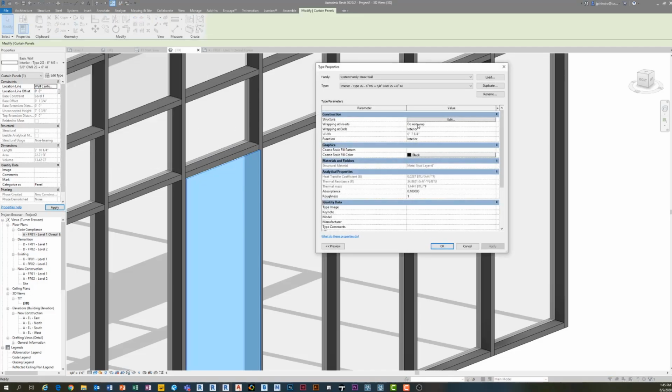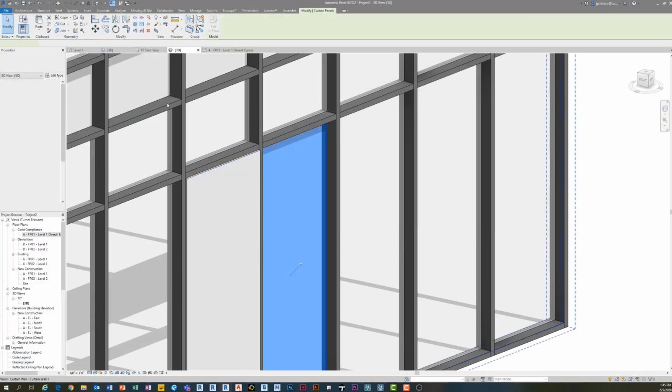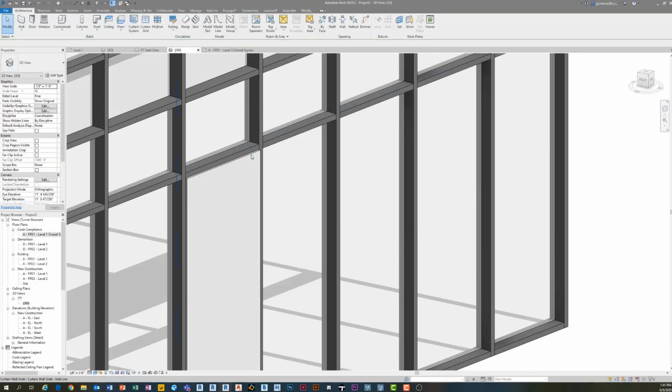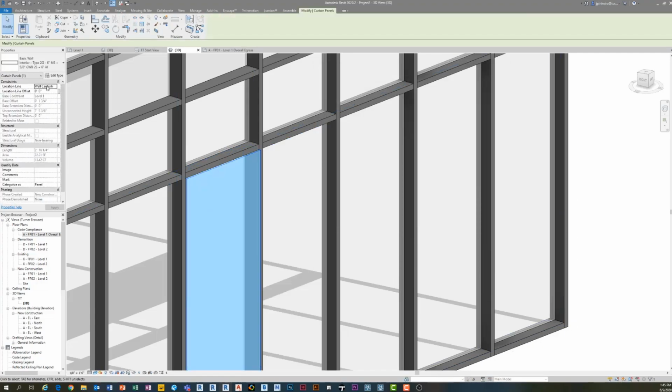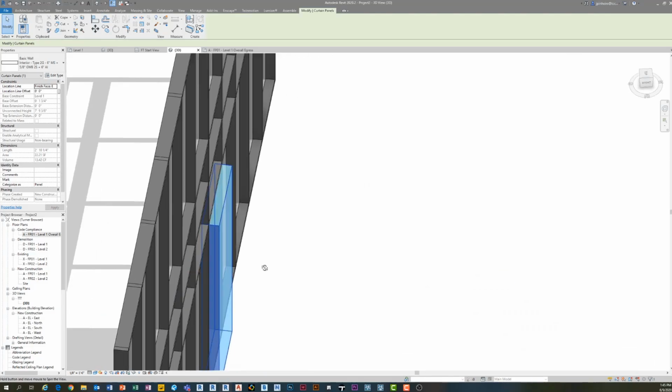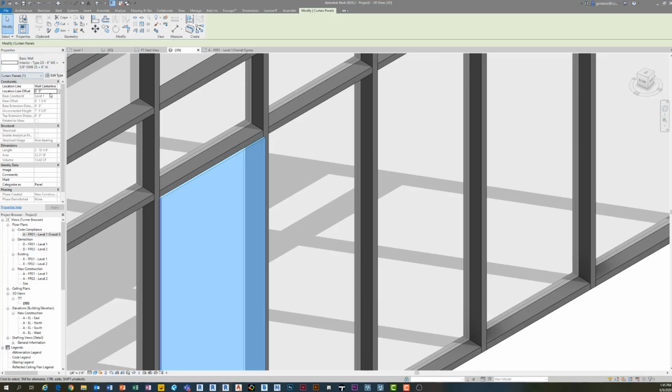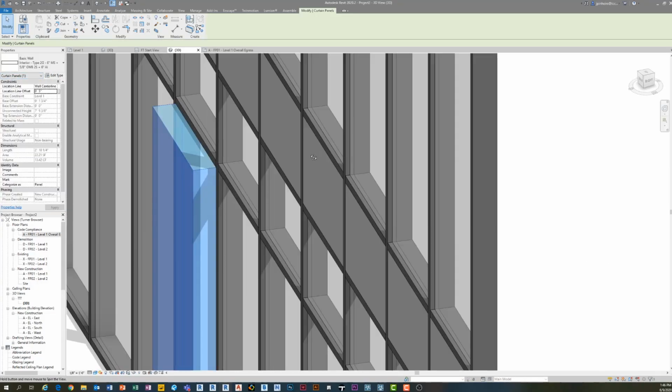So normally, right, you would go into edit type when you use the panels. And so let me back out so everyone can see that. So if I go to edit type in the panels, there's an offset right here. With walls, remember walls have finished face, center line, all that good stuff, right? So you can set how you want it to be adjusted to the center of your wall. So if I do finished face exterior, right, now this thing is aligned to the middle of my curtain wall using the finished face exterior. But if I want to use wall center line, it's there. And then if I want to adjust it, I can go either way. I can go 6 inches, 5 inches, whatever makes sense for you. 5 inches, there we go. So now it's sliding back and forth.